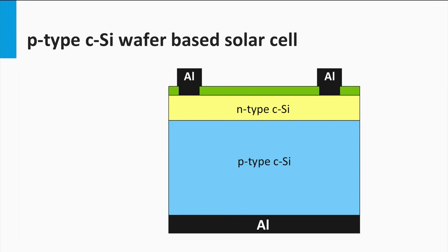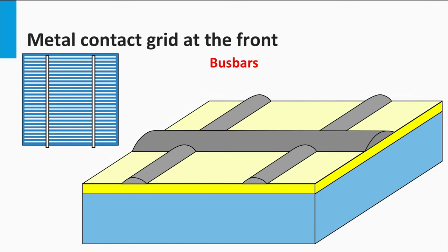In the figure, you see that the contact area between the metal and the semiconductor is kept as small as possible. The sides of the metal contacts are buried in the insulating passivation layer. The area below the contact has been heavily doped. These two approaches reduce the recombination and collection losses at the metal contact.